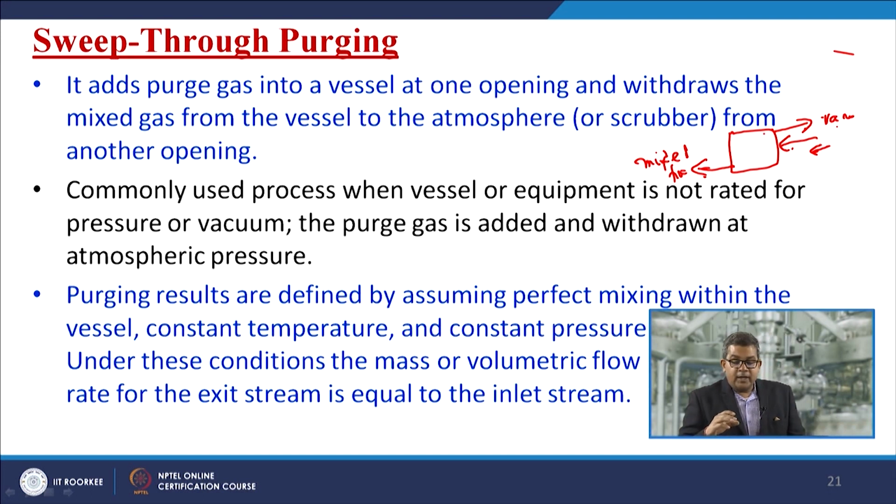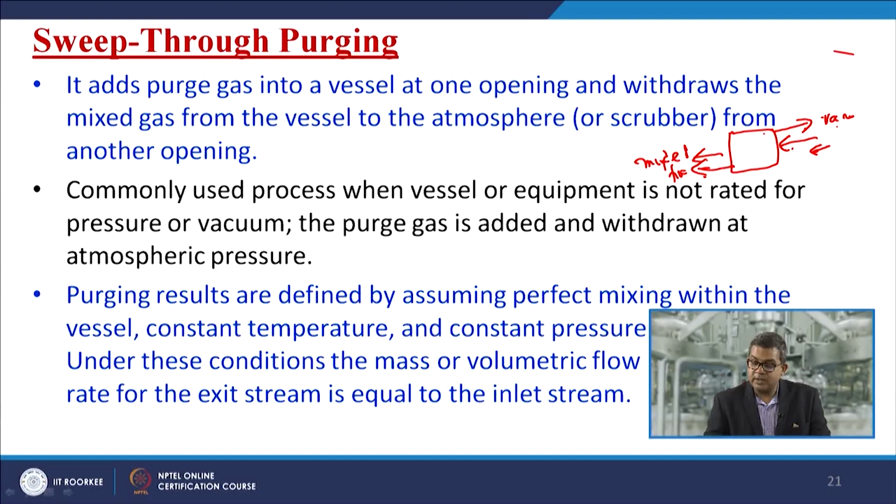One time in one phase we are having the advantage, another phase we are having a certain disadvantage. The disadvantage is that whatever mixture is coming out from this, we need to treat this mixture appropriately. It may form an inflammable mixture, so it may create a problem at the exit port. Sometimes it may have some toxic material, then again we need to go for the scrubbing system.